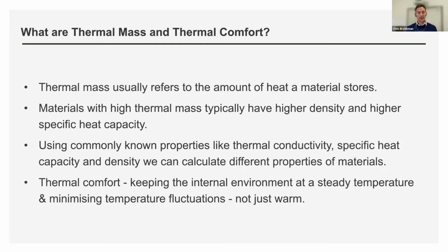So firstly, thermal mass. What is thermal mass? It's a bit of a colloquialism because it's not really a technical term as such, but when we talk about it, we're usually referring to the amount of heat that a material stores. Now, the materials that store the most tend to be materials with very high density, but also high specific heat capacity. So those two properties combined allow a material to store quite a lot of heat.